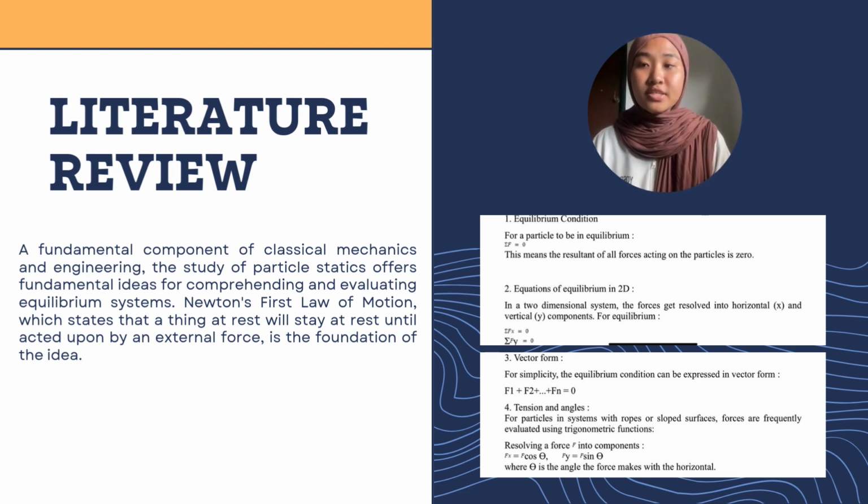For extension and angles, for a particle in a system with a rough or slope surface, forces are frequently evaluated using trigonometric functions, resolving a force F into components. Fx equal to F cos theta, Fy equal to F sin theta, where theta is the angle the force makes with the horizontal.